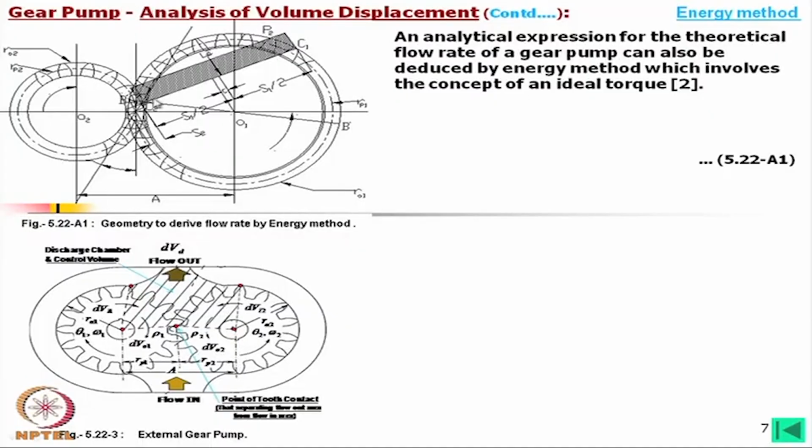By that way, we can find how much resultant load is acting on this line at the midpoint, and from that midpoint we have a distance to the center of the gear. So, if we multiply that distance by this load, we will find a torque. That torque is acting on this gear.